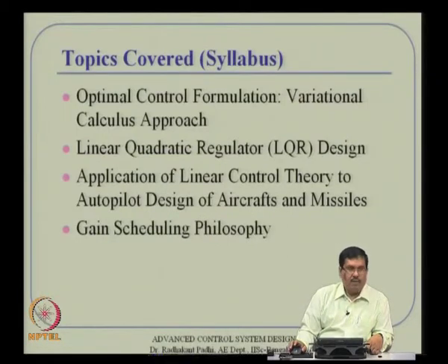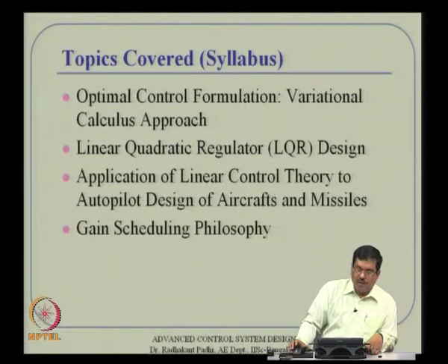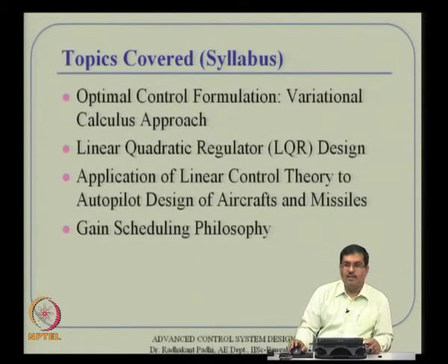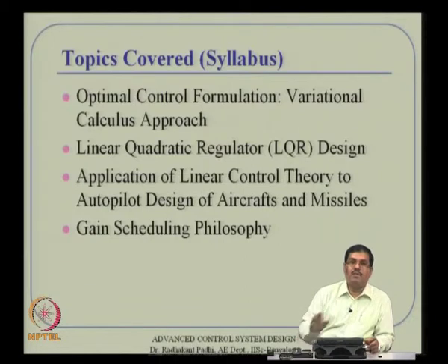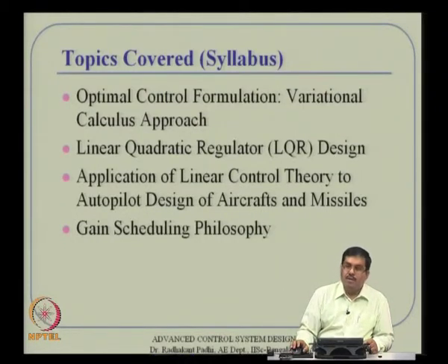Next, we will talk about nonlinear control design philosophies, and the first thing that comes to mind is what is called gain scheduling. In other words, you select several operating points around which you find some sort of linear approximation. We design specific gains for all those operating points, and then we stitch them together through some sort of interpolation routine. That interpolation gives us a nonlinear control design called gain scheduling. We will talk about that in a quick overview sense.